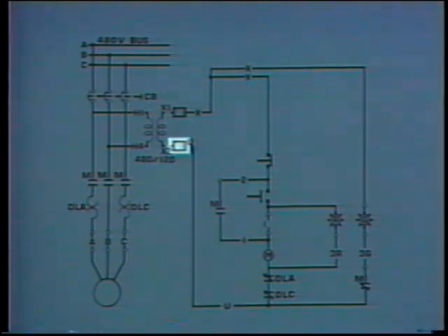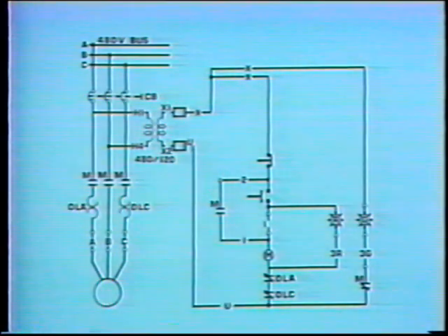The only components that are directly affected by pushing the start button are the operating coil and the red indicating light. Therefore, in this controller, it is likely that a short occurred in the operating coil or red indicating light. A ground, however, could occur anywhere in the control circuit. The electrician decides to test for grounds first.